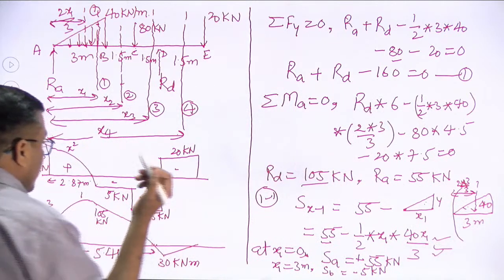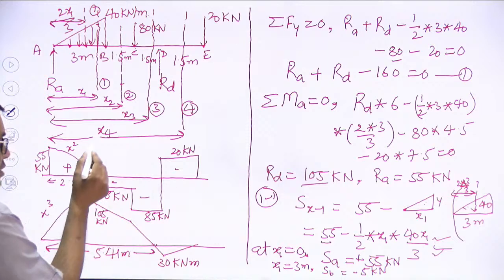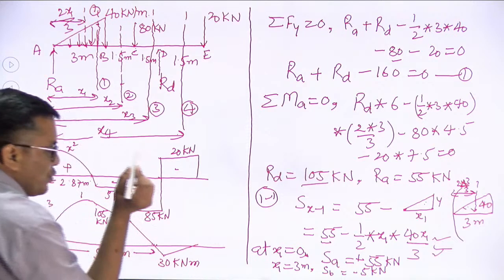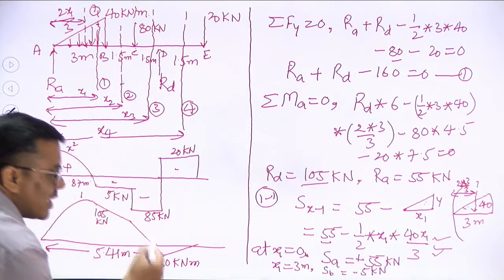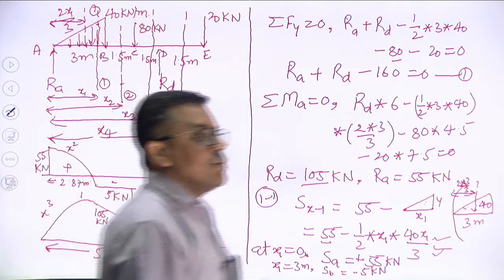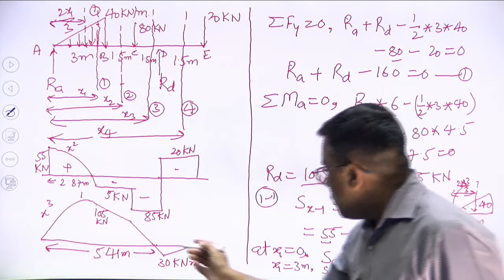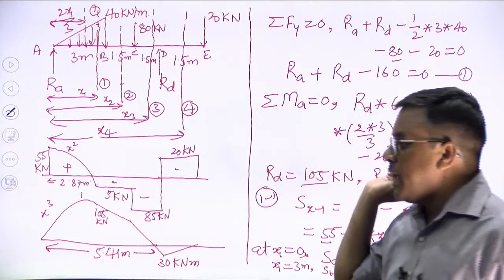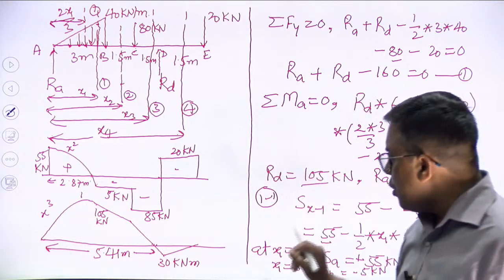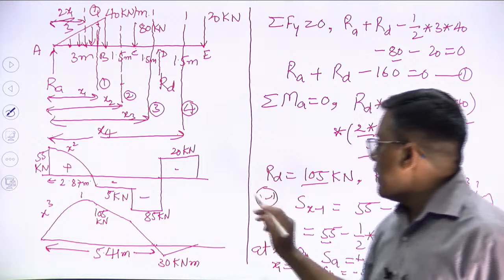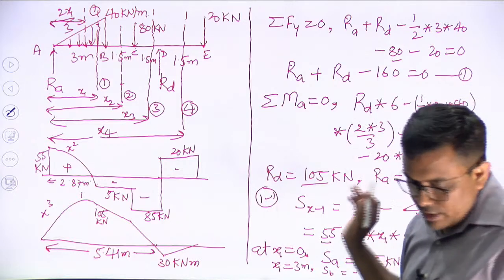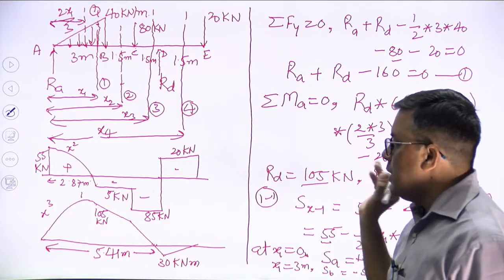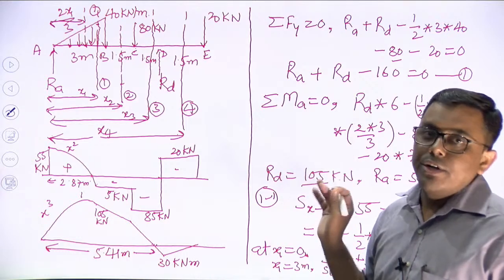यहां पर दोनों ही है, at this point it is maximum और यहां पर भी तो shear force 0 हो रहा है, so it is minimum, -30 it is coming out. Okay, so this is the point. Then if you are getting any point in the bending moment diagram where bending moment is 0, so that point is point of contraflexure. इतना काम यदि आप करते हैं then you are eligible for 10 on 10 marks.